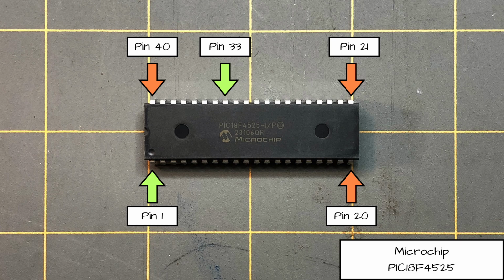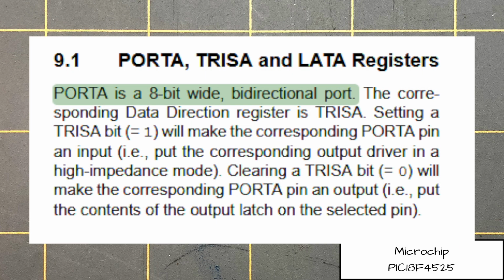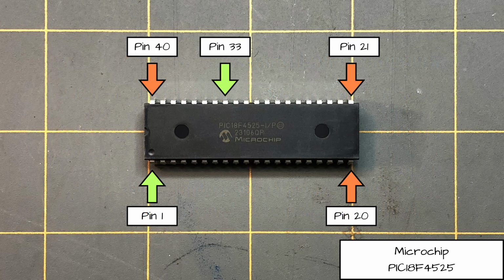Since the PIC 18F4525 is an 8-bit PIC, it has up to 8 bits on each port, ranging from bit 0 to bit 7. Referring to pages 91 through 92 of the datasheet, we can learn that port A is an 8-bit port, and that pins RA0 and RA1 are 2 of 8 total input-output pins on port A.